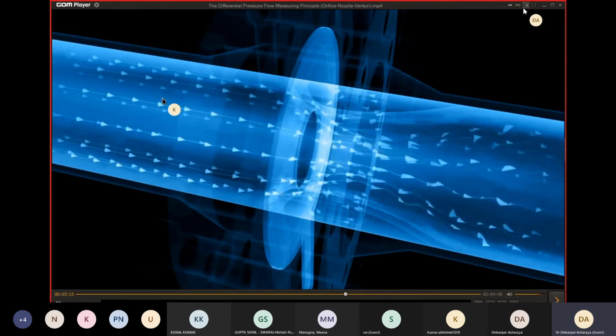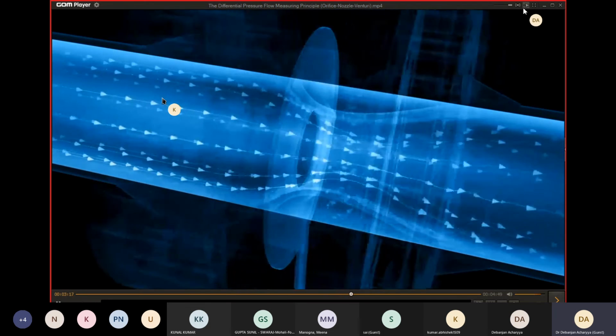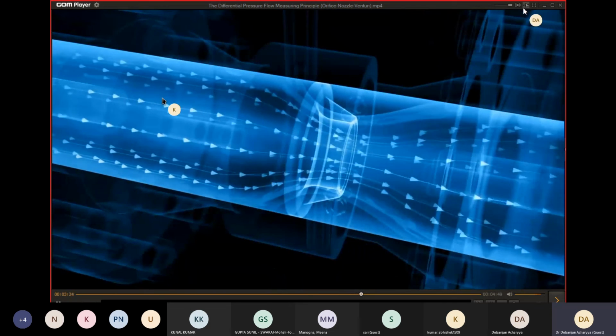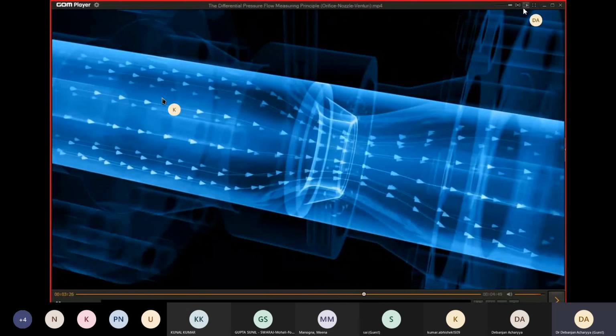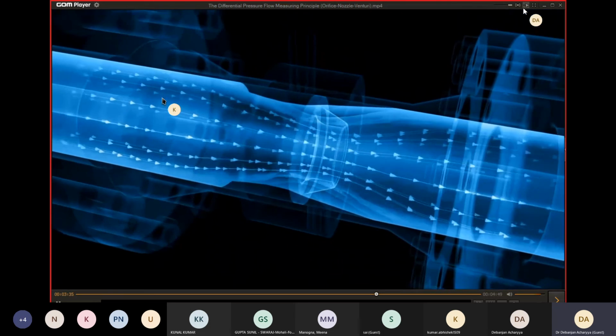This demonstration shows that an abrupt restriction generates severe turbulence in a fluid. Nozzles with a rounded, funnel-like inlet clearly reduce turbulence and thus create less pressure loss. Nozzles are particularly suitable to higher flow velocities or to fluids with abrasive solid particles.